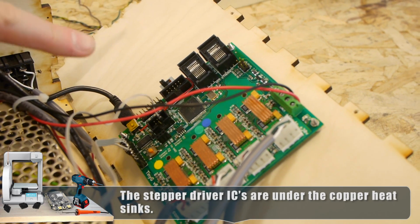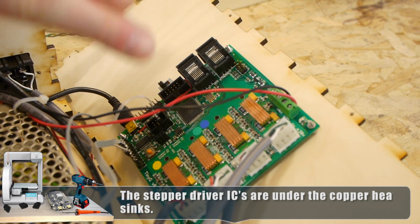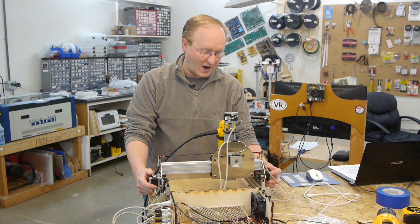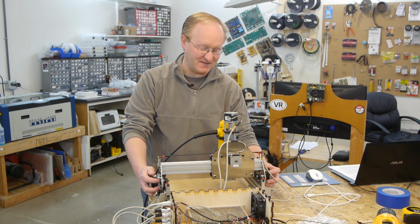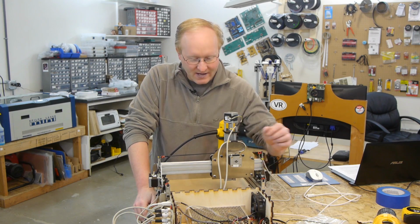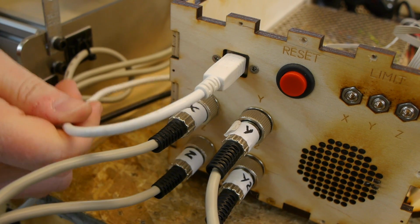It has a microcontroller on it, a bunch of input-output, a USB connection, and these 4 plugs are for the 4 stepper motors. So we have actually 2 Y motors. That way it's basically easier and cheaper to put a motor on each side and drive them at the same time than to try to make a linkage for a single motor. So we have all this ported out nicely to some plugs in the case here, and they're nicely labeled so we know where everything goes.